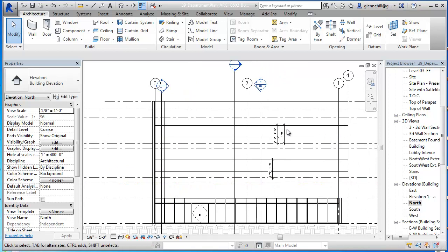And so I'm going to have more structure in here, but at least I'll use that as the beginning. And now we're probably going to need some structure about every 10 feet. There's only certain sizes that mesh screen can be bought in, so you've got to have structure between each of the mesh screen areas. So I'm going to create some more verticals here. The horizontals are probably fine. I've probably got enough horizontal structure in there to not be concerned.